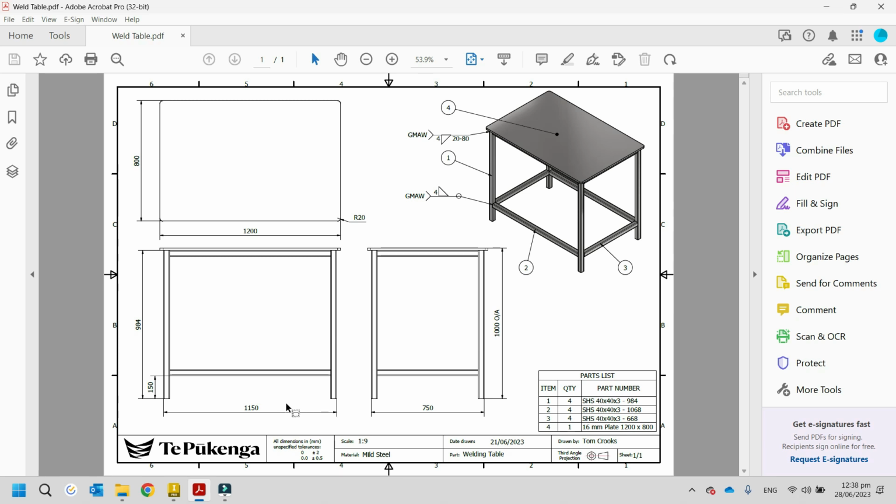So what I'm going to do straight away is work out the center line measurements for these things so that I can draw a box that I can base this all around, because the frame generator works a lot easier off center lines. The other thing you could do is draw a box and then create a frame on it and then change the size to suit. But we might as well work it out since we've got a given dimension here.